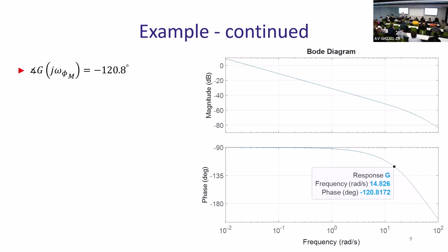All right? So this is how you know. So we got that by subtracting 180, right? Yes. So if we wanted any point, we would subtract any number. No, you're always subtracting 180, because this is what phase margin is defined by. It's distance from 180. You're always subtracting 180, actually negative 180. So this is exactly the distance that you're looking for. You are prescribing the distance to be whatever you want it to be.